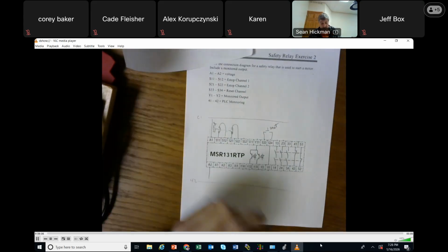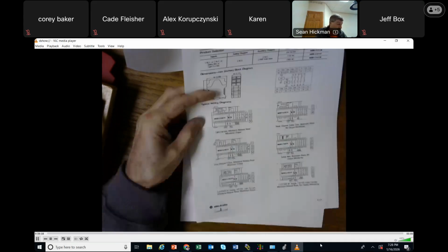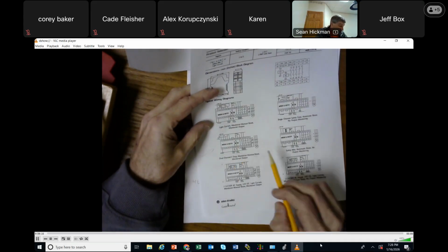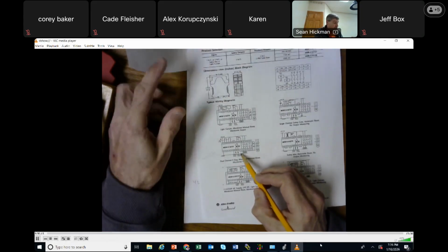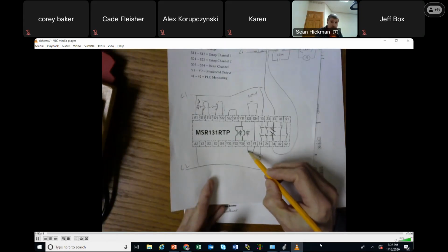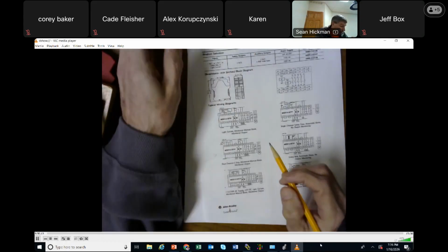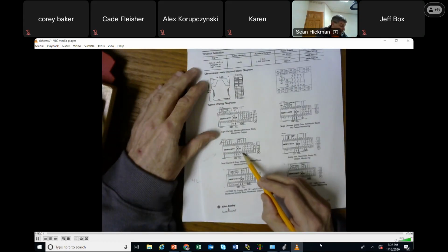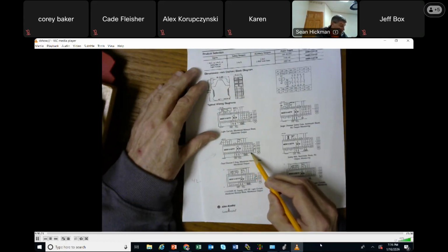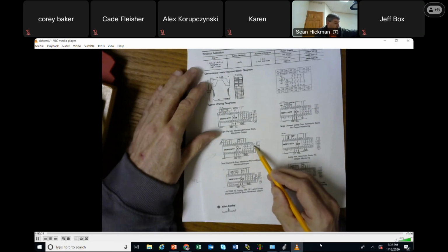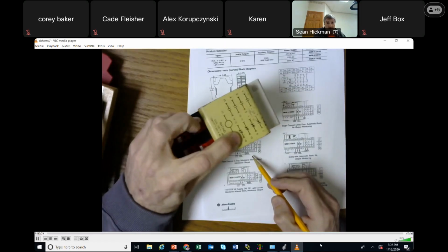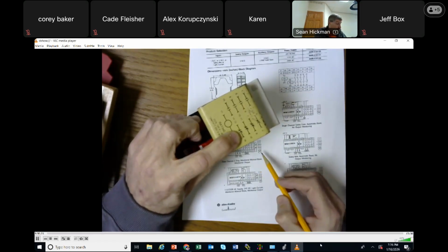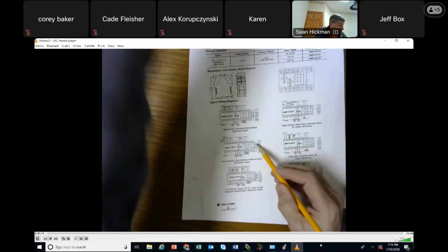And if I go to this middle one again, before we jumped Y1 and Y2 together, we just jumped them because there was no monitoring, okay? Well, now what we're doing is we're running Y1 and Y2 through the closed contact of the motor starter or the contactor, okay?